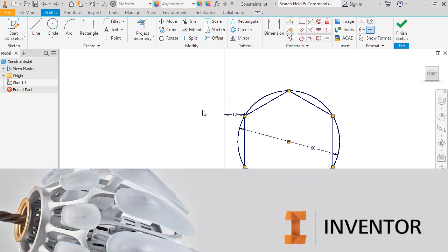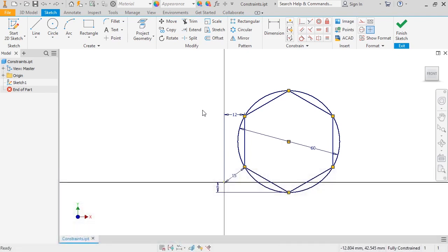You can use constraints to relate sketch segments, model geometry, and the center point or origin of a sketch. Constraints are key to parametric modeling since they can be used to constrain sketches alongside dimensions but are more flexible to updates. For this example, I'll delete all existing dimensions. And you can see that the status bar says I need 4 dimensions. As I mentioned before, this doesn't mean numeric dimensions, but instead references the degrees of freedom in the sketch, and will decrease as I add constraints.